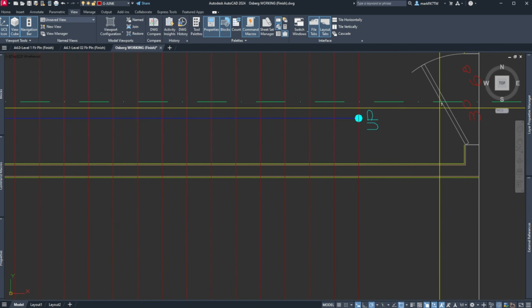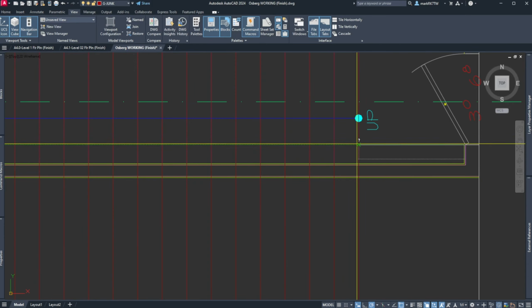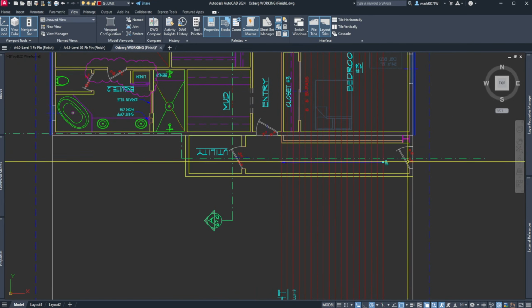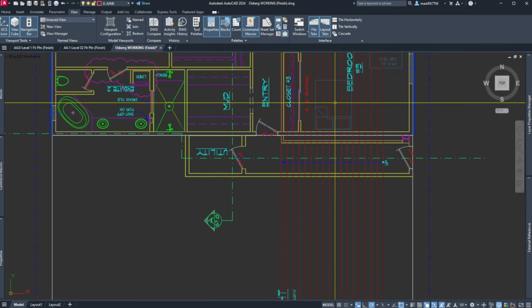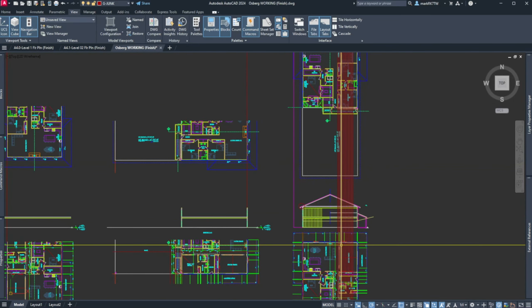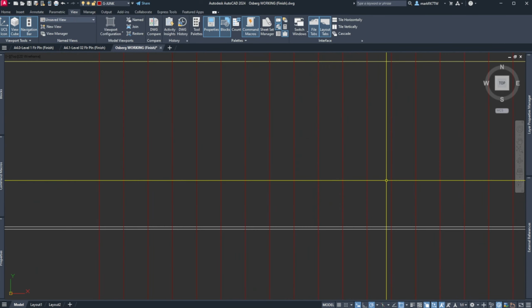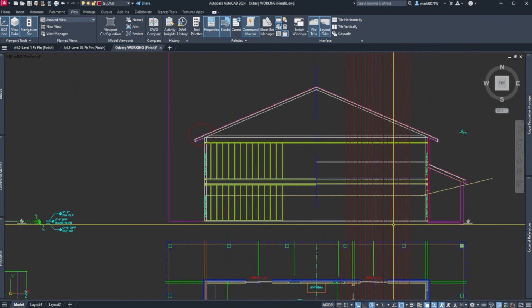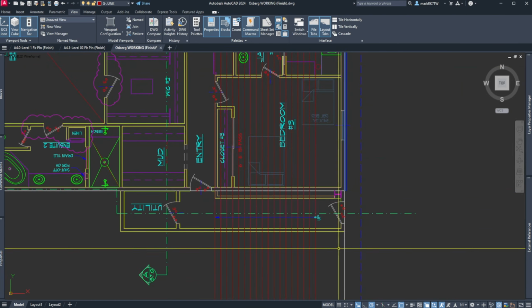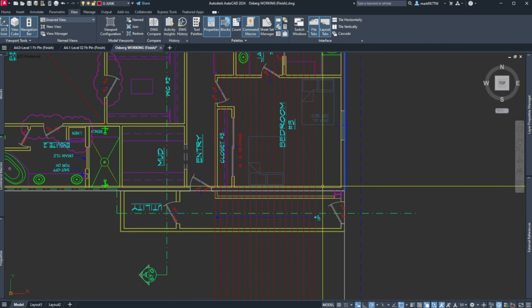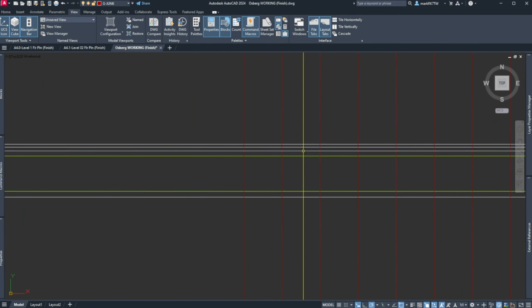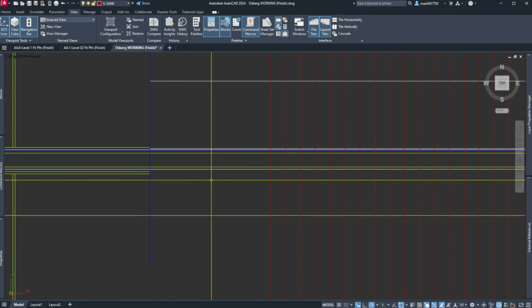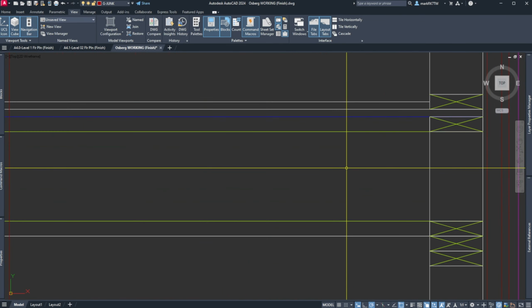Check my distance here. Let's make sure I've got at least 3 feet. At the bottom of a stair run and at the top, you've got to have a 3 foot by 3 foot minimum area. So now we'll come down to the bottom. And okay, so this is going to be our first step up. So that's your first step up. And my absolute distance, let's just see what I have got drawn here.